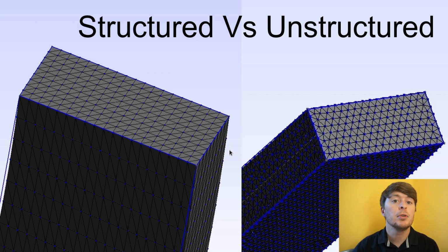And that's very important when we come to consider different CFD or computational fluid dynamics problems. The reason why we might want to do a structured mesh versus an unstructured mesh is because we're looking at a certain type of dynamic, or we want to reduce the amount of elements in our mesh and make them more efficient towards the dynamics we're trying to see.